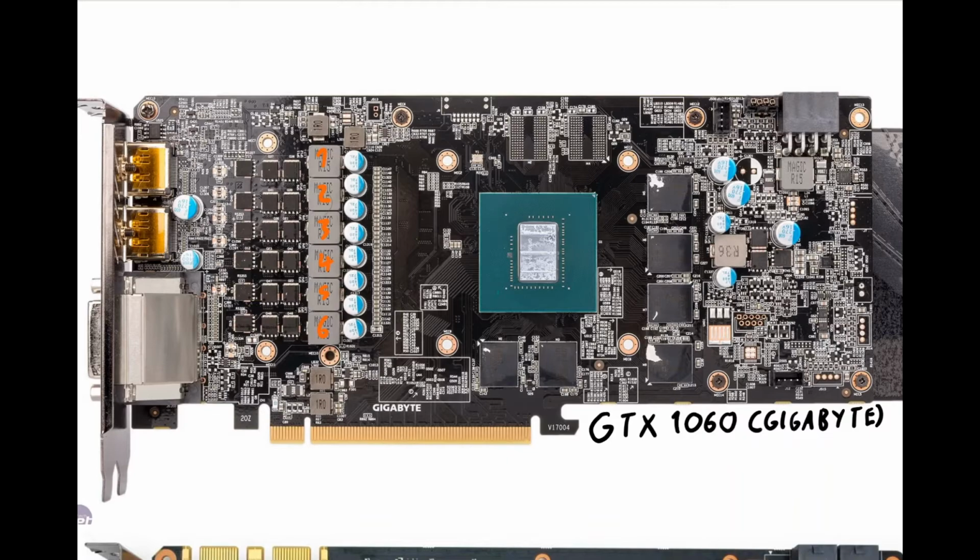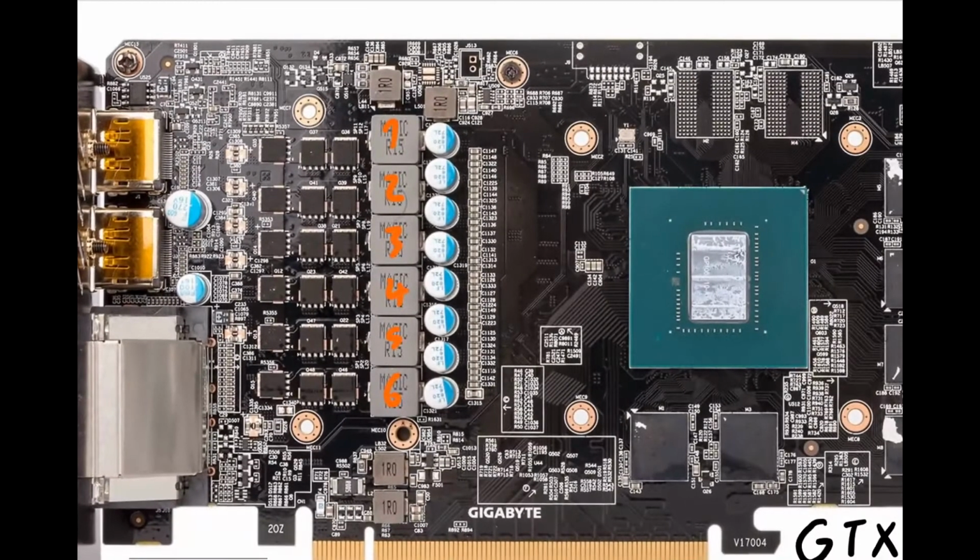And then we see our MOSFETs. This card is using discrete MOSFETs, and what you're going to see a lot of the time is that you have 2 low side MOSFETs, because your low side has to handle a lot of current. Those 2 low side MOSFETs will be put in parallel, and if you put them in parallel, each of them only has to handle half the current because it is split between the 2. So you have 1 high side MOSFET per phase, and then you have 2 low side MOSFETs per phase.